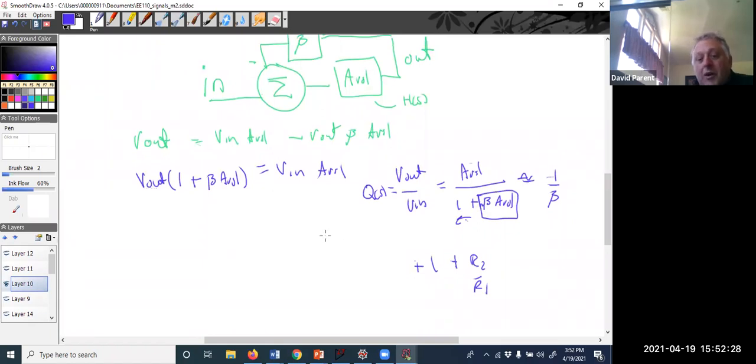Now, what if this open loop gain was open loop gain divided by S, right? Wherever there's that, now I can put the S, but really I get the original numerator times the original denominator, S, plus the feedback term times the original numerator.